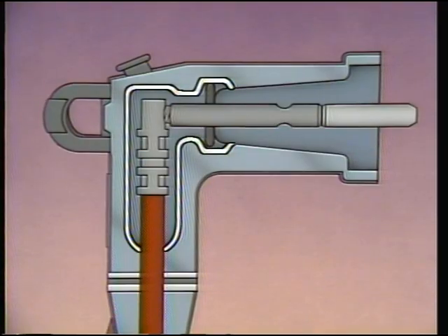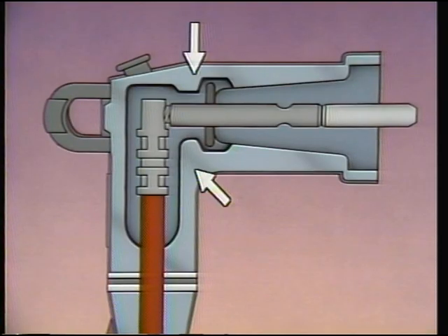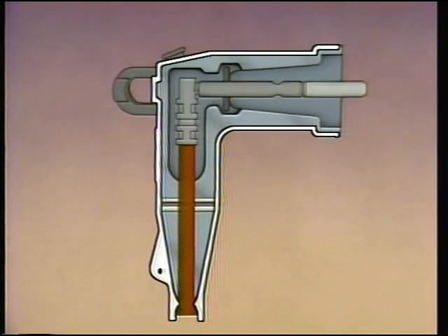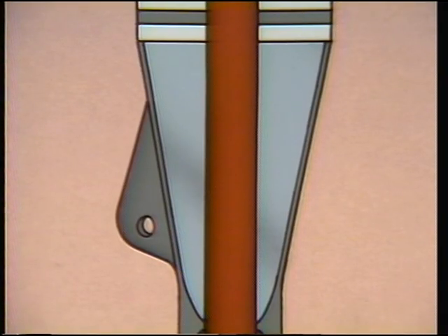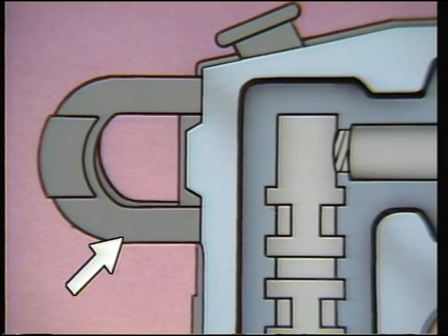The conductive insert shield surrounds the area where the cable connector enters the elbow. The layer of insulation over the conductive insert shield insulates the connection to the equipment. The layer of semiconductive material over the insulation layer reduces areas of stress concentration on the insulation. Any static charge that builds up on the semiconductive material is bled off to the cable's metallic shield layer through the grounding eye. The pulling eye is where a hot stick can be attached to control the elbow during switching.